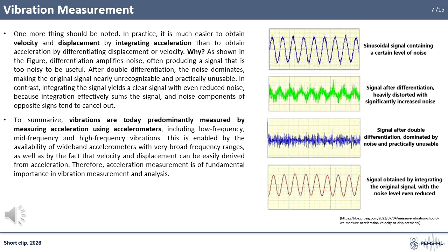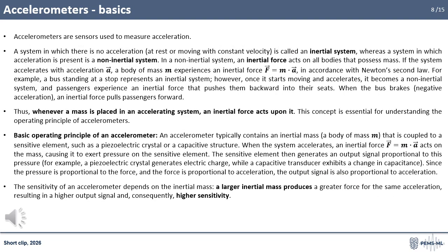Therefore, velocity and displacement are most reliably obtained by integrating acceleration. As a result, vibrations across all frequency ranges are now predominantly measured using accelerometers, making acceleration the fundamental quantity in vibration analysis. Accelerometers are sensors used to measure acceleration.